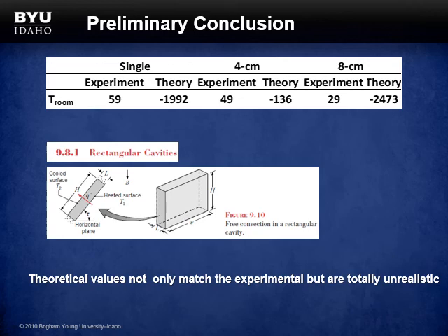Our next approach is using equations from rectangular cavities. That is section 9.8.1 of Fundamentals of Heat and Mass Transfer. At the same time, we request your opinions, ideas, and suggestions of sections, equations, and principles that we should consider in our next approach to calculate these internal temperatures.